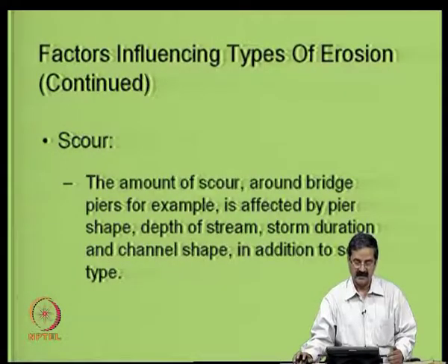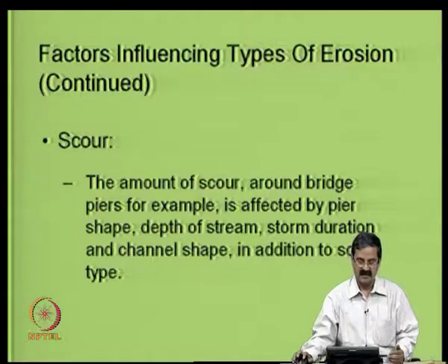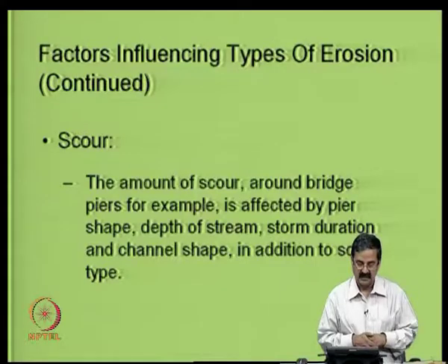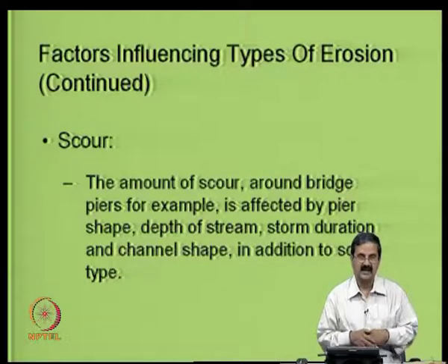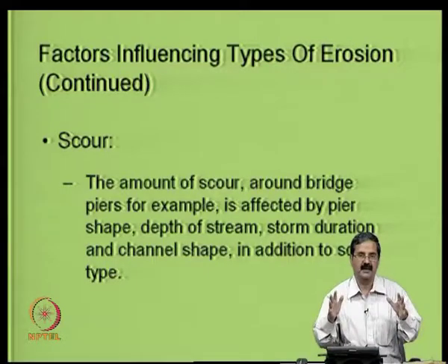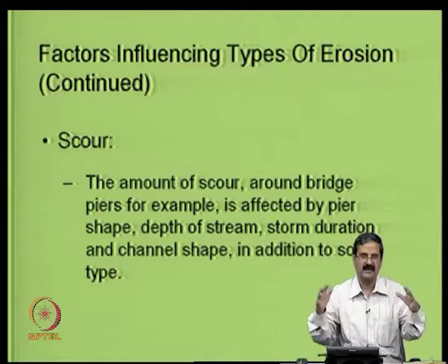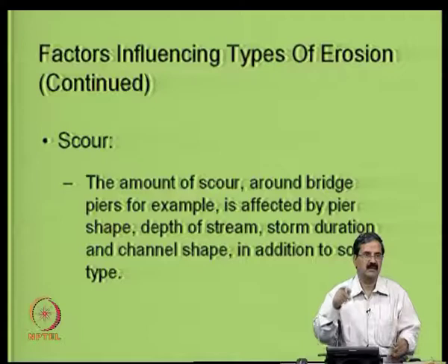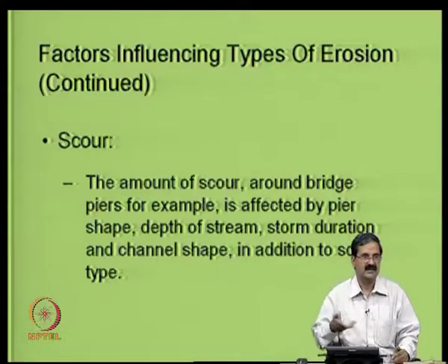Another important thing is scour, a standard issue similar to our tsunami-resistant structures, where the amount of sand that gets removed is an important problem. Around the bridge piers, you would like to see that there is a confinement effect in bearing, where we calculate the foundation bearing capacity with gamma d into F. Surcharge effect is considered.